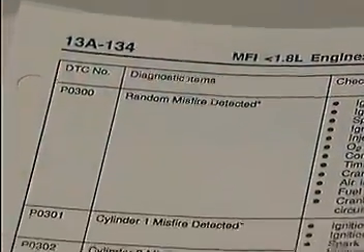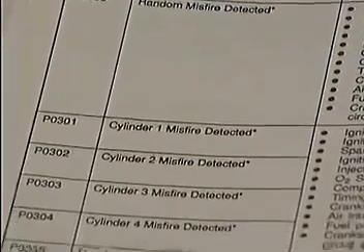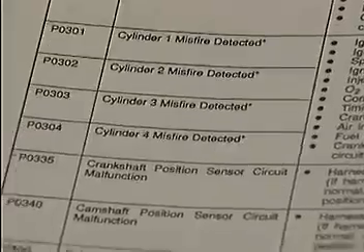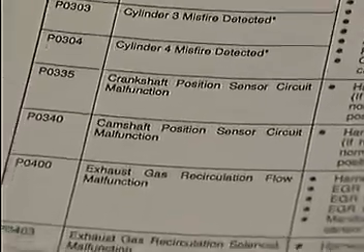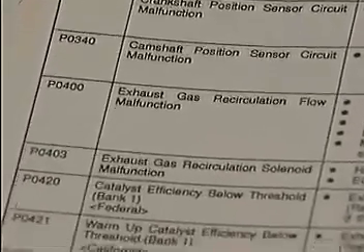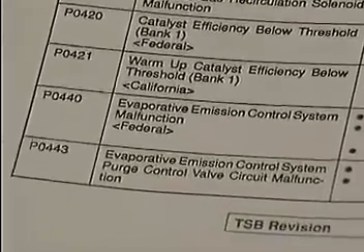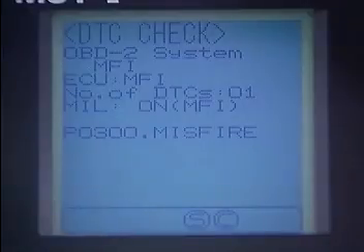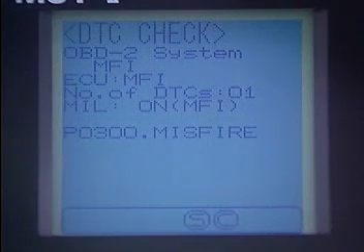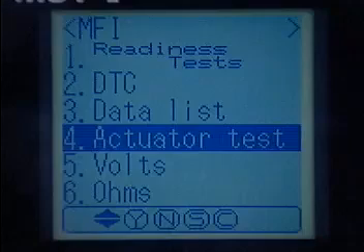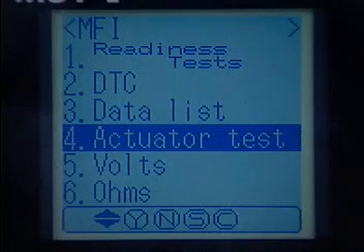For example, a Mirage with a 1.5-liter engine and automatic transaxle has 45 P codes available. With the 1.8-liter engine and automatic transaxle, 47 codes are available. If a code is not available in Mitsubishi Scan Tool mode, the Scan Tool will display the code from the GST mode. Along with new codes, additional engine and transaxle service data and actuator tests have been added for the